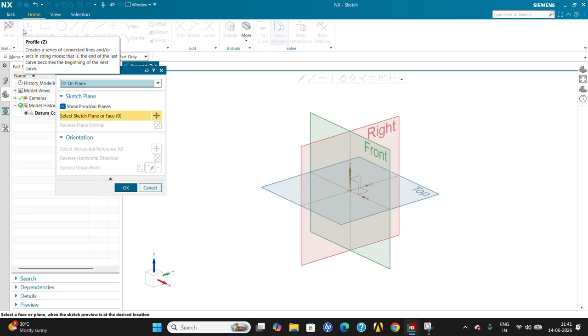Which side of the sketch is required, we need to decide depending on projection. Which projection: third angle or first angle. Depending on that we are selecting the planes. Maybe with the first angle method we require the front view. By seeing the first angle projection and third angle projection, we can understand in which direction, in which sketch we need to put it. Then accordingly, we need to create the sketch.